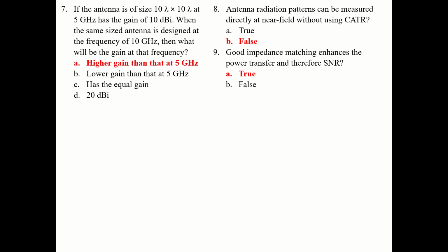Next: good impedance matching enhances the power transfer, and therefore the SNR. Yes, correct, because the amount of power getting reflected is reduced when you have good impedance matching, so the power transfer improves, which in turn results in improved SNR. But it is not the only factor. It is one of the factors that improves the SNR, because SNR is a function of many parameters. We should not confuse that. You should keep that in mind.